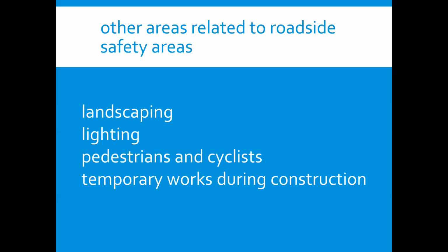The benefits of a high level of street lighting, especially at urban intersections, are well documented with a strong correlation to nighttime accident reduction. Street lighting should be substantial enough to provide the driver with a clear view of the road alignment in the urban area.